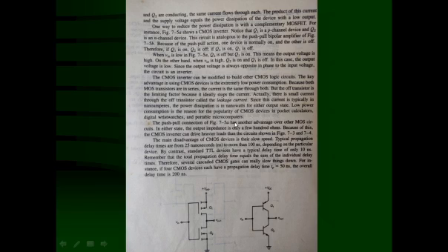and portable microcomputers. The push-pull connection of figure 7.5a has another advantage over other MOS technology circuits. In either state, the output impedance is only a few hundred ohms. Because of this, the CMOS inverter can drive heavier loads than the circuits shown in figures 7.3 and 7.4. So compared to NMOS technology or PMOS technology or an inverter with a passive load, here the output impedance is very low due to the push-pull arrangement, and hence it can drive a heavier load.